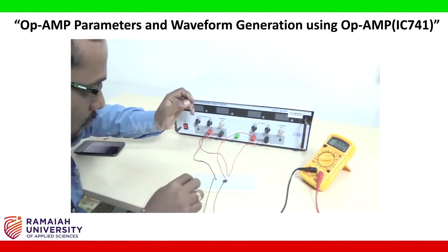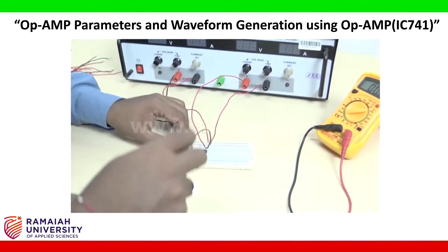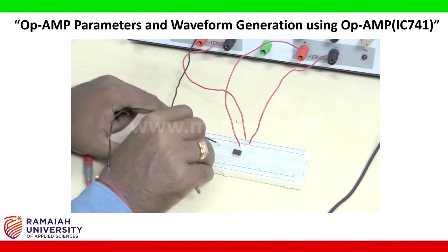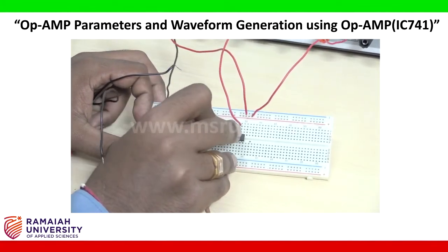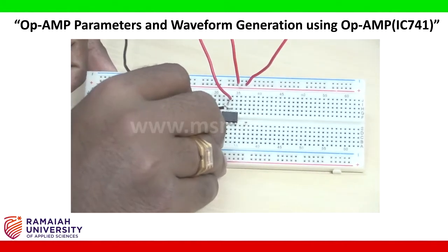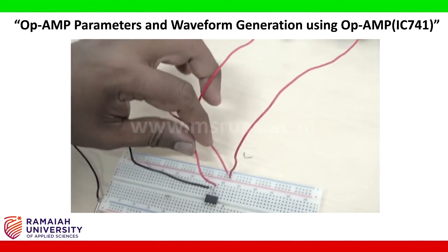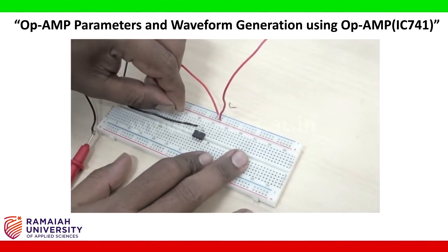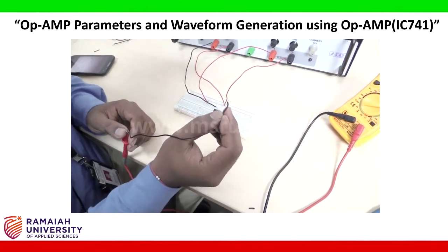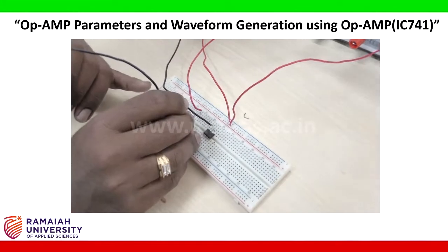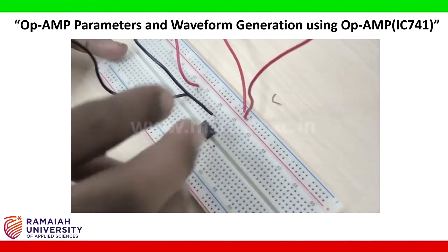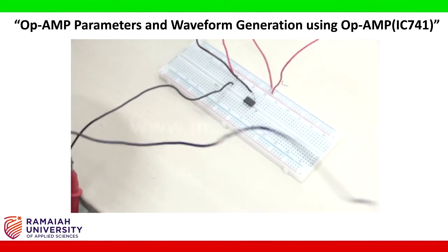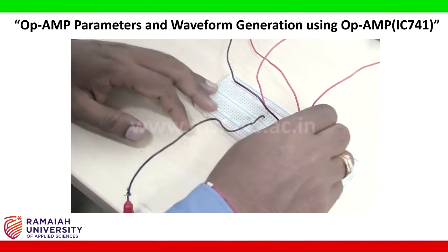How to do this? We remove the connections of this multimeter, and I connect this VD1 in the same position back to terminal 2. The VD2 positive terminal I connected somewhere in the circuit board. I take the multimeter positive and make it in series with the VD2 terminal. I take the negative terminal of the multimeter and connect it to the ground.